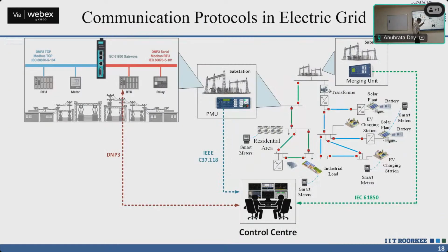Now regarding the overview, Professor Sidhu has already told you about IEC 61850, and he also talked about DNP3. So if we compare DNP3 with C37.118, which is for PMU to PDC, and of course 61850, how can we compare these things?